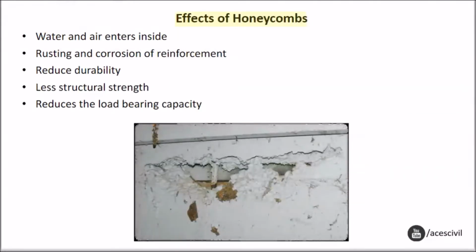Effects of honeycombs. Water and air enters inside. Rusting and corrosion of reinforcement. Reduced durability. Less structural strength. Reduces the load-bearing capacity.